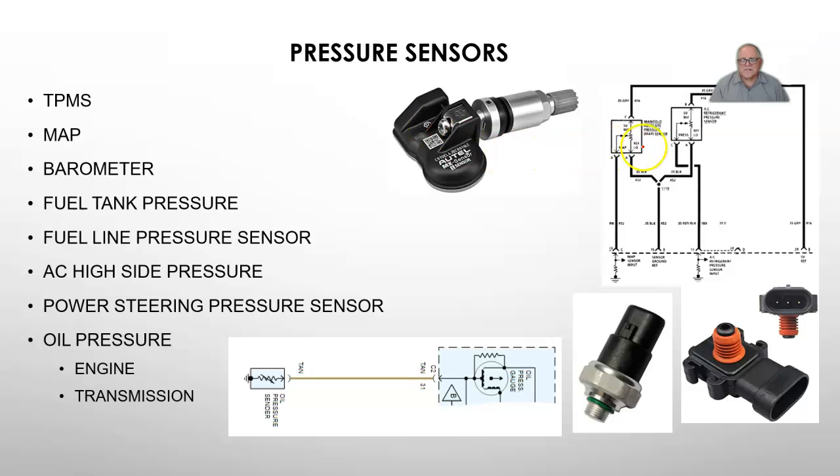On the MAP sensor, this is the one that's behind me here. We're going to look at this one on the left-hand side, and what you're going to see is 5 volts are going to be applied to the sensor. What you will find is most all sensors on the vehicle operate within a range of 0 to 5 volts. They're 3-wire sensors. Reference is going to be 5 volts. Ground, which you need to make sure is a good ground, and then our signal. From our MAP signal, if key on engine off, put the scan tool on there, you should see about 4.5 volts. The higher the altitude, the lower the voltage is going to be. Start the car up, you should see between 0.5 and 1.2 volts with the engine running.